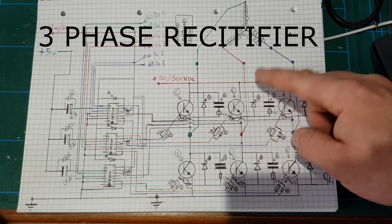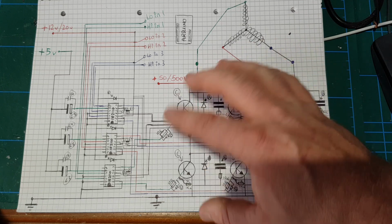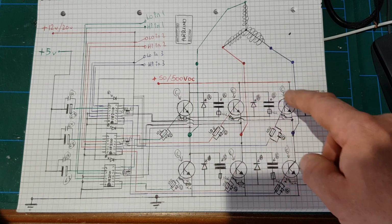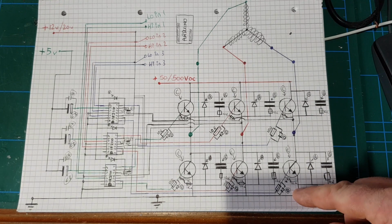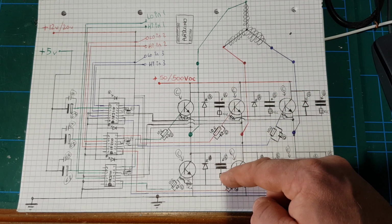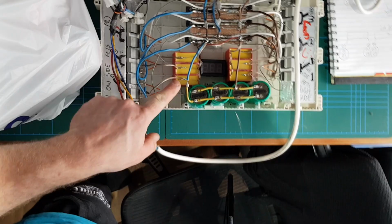AC, I mean, it does the job of both. It'll regen and it will act as a snubber. Any transients in any direction will be rectified back onto the DC bus like this. So we already looked at that in the last video, actually. And these are the 3 red capacitors, 220 nanofarads with the little 10 kilo ohm resistors. These 3, okay, that's them.